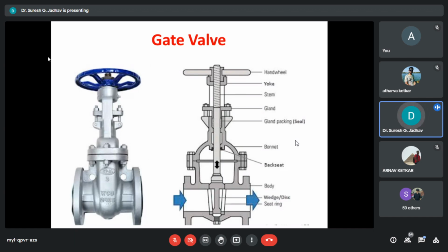The compact design small bore, that is 1.5 inch gate valves, are as per API 602 or BS 5352 unless the full bore design is specifically asked for. Manufacturers supply the reduced bore valves. The full bore design gate valves are also covered in BS 5352 and is designated as the standard bore.